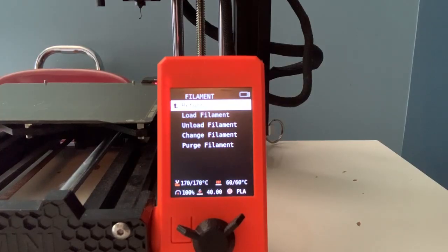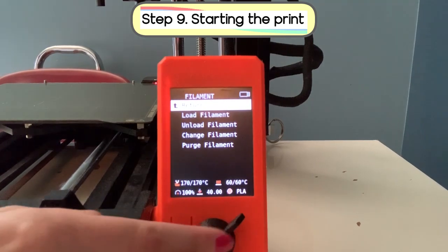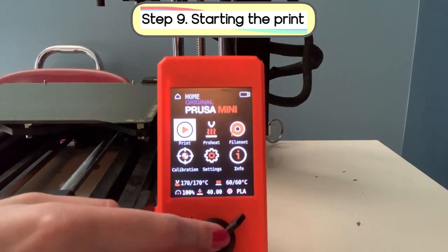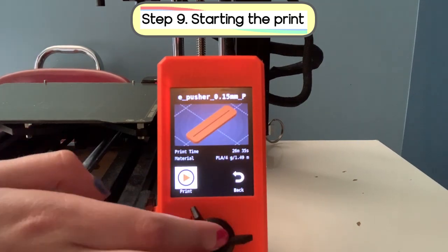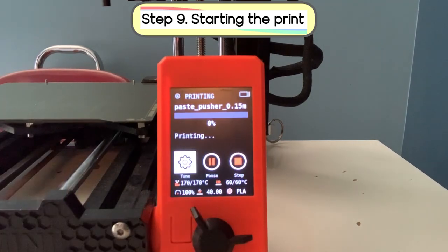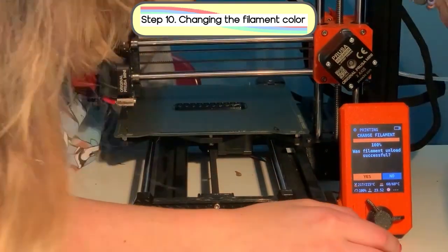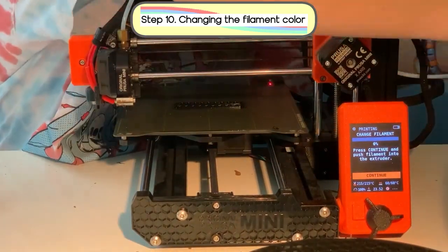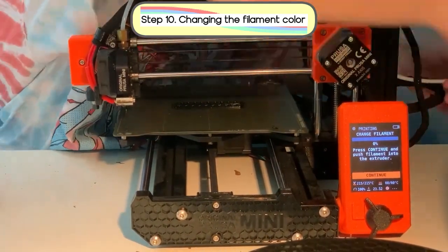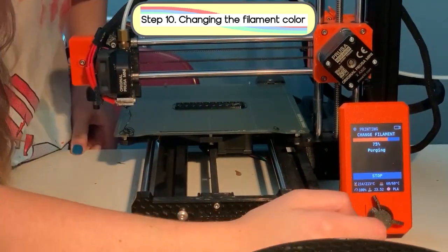With our filament properly loaded, we can now go to step 9, which is starting our print. So hit return, print, and then press that, start print. Now we're at step 10. After the print hits the layer we set the color change at, the filament will unload itself and require you to reload another filament color. Load the filament just like you did in step 8.